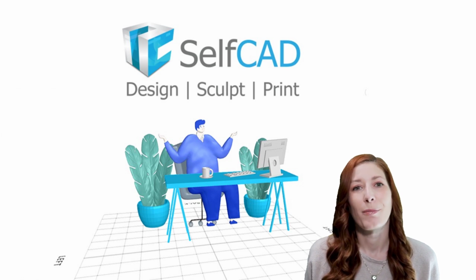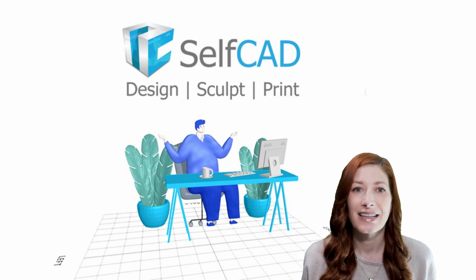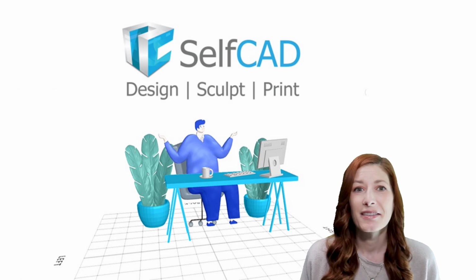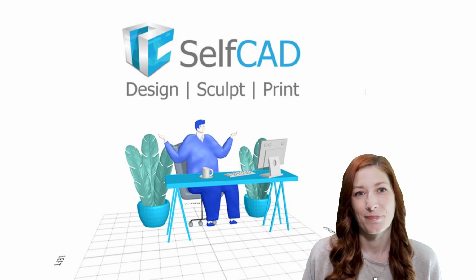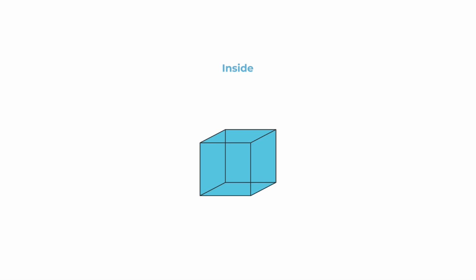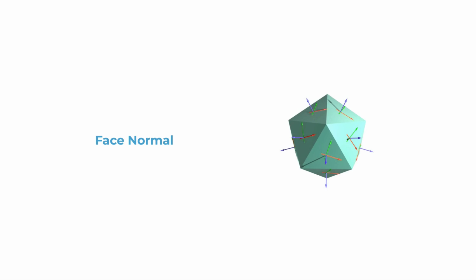The solution to this problem is to assign a different color to the inside of the object to easily spot the holes. But before we do so, let me explain the theory behind it. What are inside faces? Digital objects have the concept of inside and outside faces, determining the inside and the outside of the object. And what determines what direction is what we call face normal, which you can visualize as a vector pointing from the inside to the outside of each face. And naturally, we don't want any inside faces to point outwards.